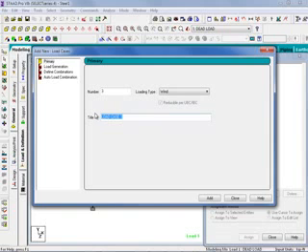We will then create our wind load case for our positive X global axis direction, and then click Add. Before leaving this dialog, we will specify the other load cases that will be required for this particular structure. Those will be wind load in the negative X direction, wind load in the positive Z global axis direction, and wind load in the negative Z global axis direction.